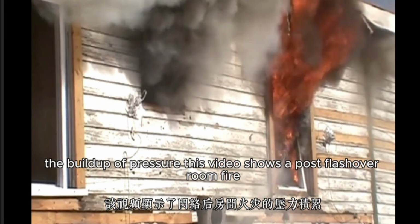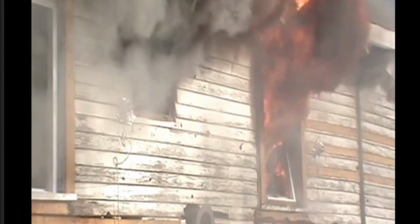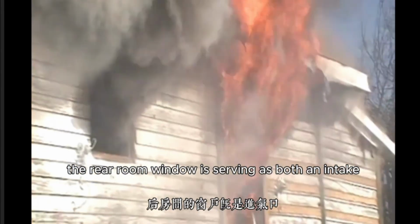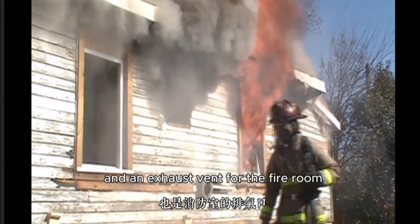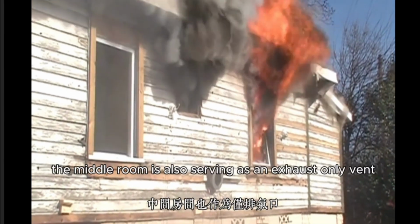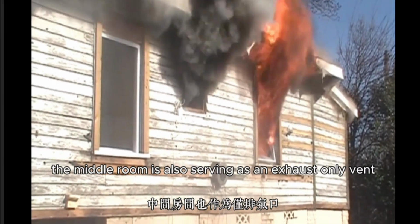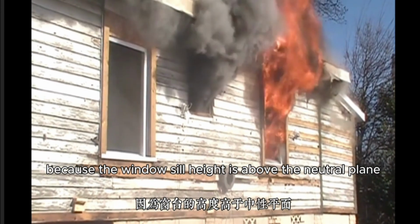This video shows a post-flashover room fire in the rear of the structure. The rear room window is serving as both an intake and an exhaust vent for the fire room. The middle room is connected to the fire room by an open doorway. The middle room is also serving as an exhaust-only vent because the windowsill height is above the neutral plane.